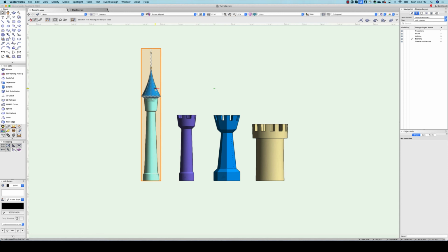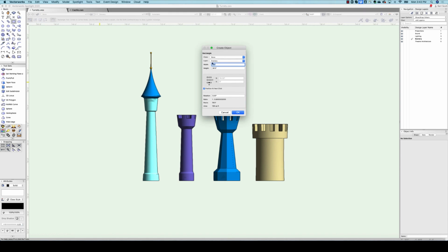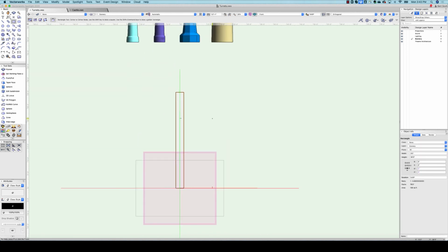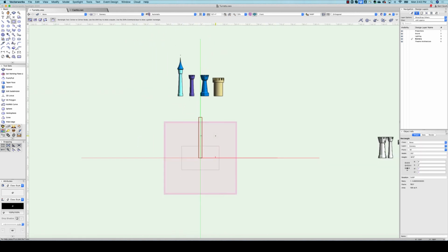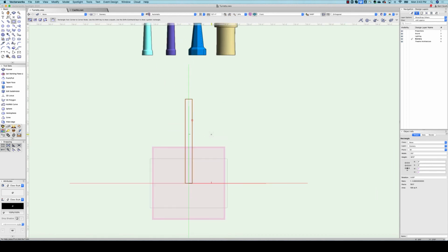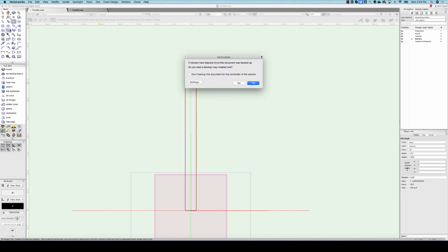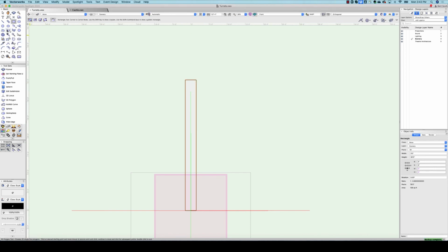It's really just a sweep. So let me measure the height of this. 36 feet. So I'm going to draw a rectangle that is 36 feet tall and 3 feet wide. And let me just say the rectangle is totally optional. I find it easier to draw within a boundary. And this is just because I'm trying to make the ones I'm drawing here vaguely similar to the ones that I had already drawn, but you don't need to draw this rectangle. What you really need to do is use the 2D polygon tool. I just find it easier to draw inside the rectangle.